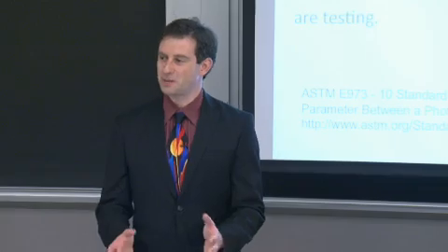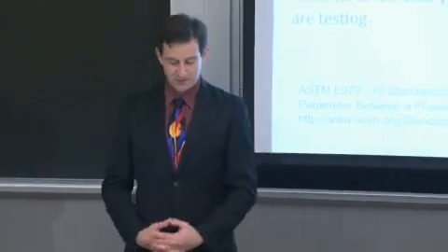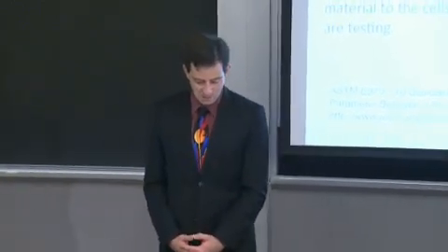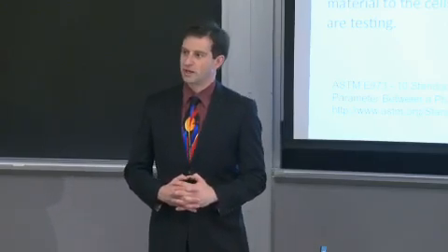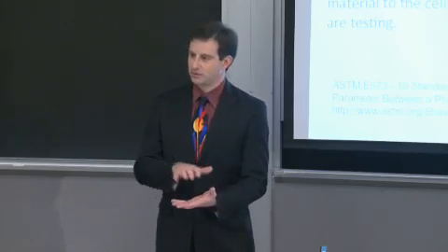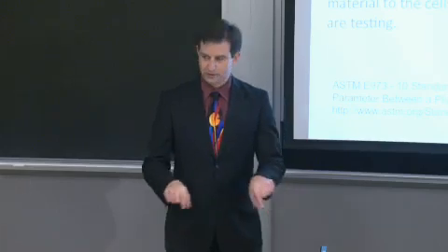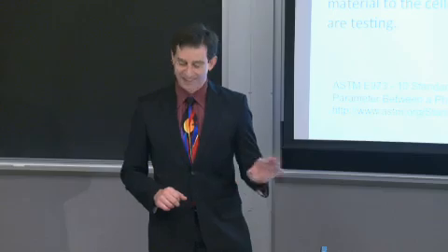If you follow a set of standard protocols that you can receive from the folks at NREL, I believe Keith Emery might be a good point of contact first. There is a very specific set of protocols that you should follow if you want to make your own in the lab. In other words, you have to design the contacts a certain way, the encapsulant a certain way, and make sure that the materials comprising the remainder are black so that they don't reflect the light back in. Little details that are only gathered by experience.